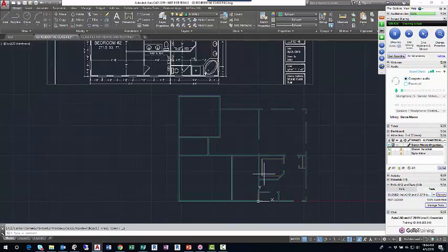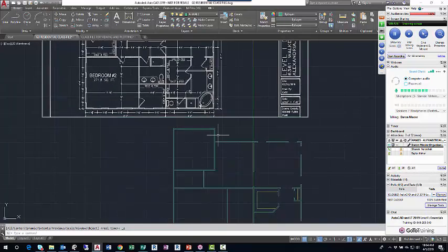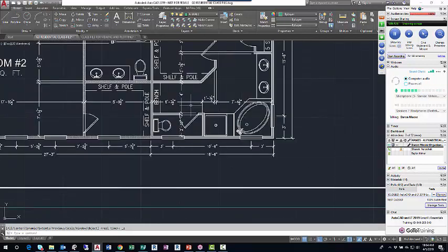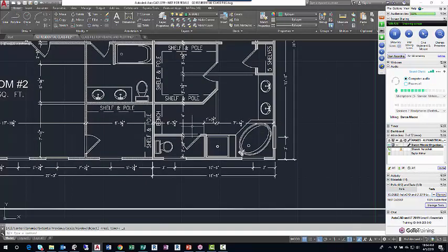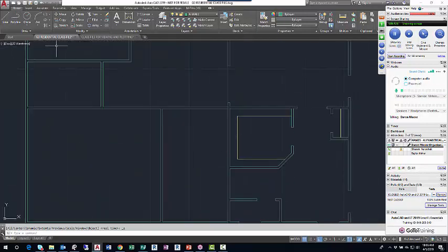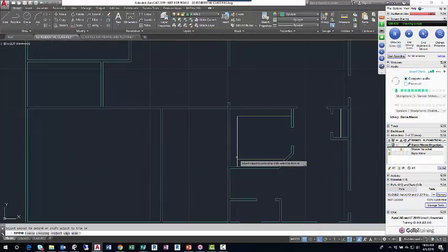And again, as you're plugging away, some of the lines can be extended from the master bedroom over to the rest of the floor plan. Namely, the bottom wall lines of the walk-in closet can be extended to create a separation between the hall closet and the hall bathroom and the bedroom 2 closet. So I'll just use the extend command. Open up where trim is, extend, enter.